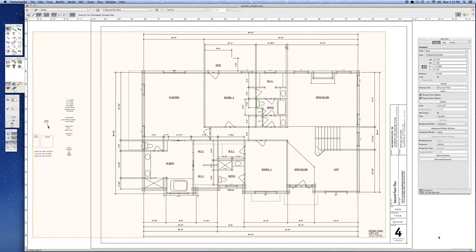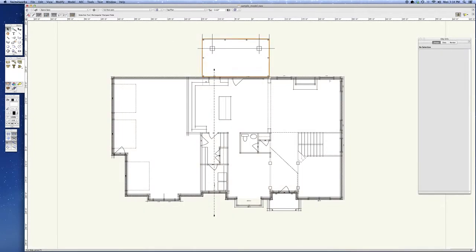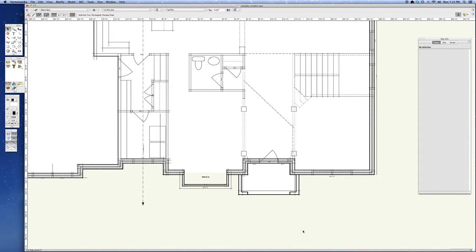At this next phase, though, we're going to start to add just a few walls and roofs and floors just to give a basic exterior model to the client so that they can see what it's beginning to look like with some 3D geometry. So to do that, I would go to the saved view of working one to work on the first floor. Now, I've already put the floors and the walls in here, but not going to place any doors, no windows, just doing the actual most basic shape.